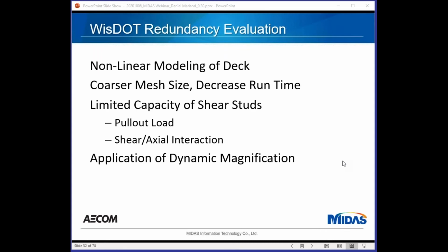So we had to make sure that those shear stud elements had not only pull-out capacity, but some sort of shear capacity. And then also we had to find out, when something breaks, we all know that there's a dynamic effect. So it's not only the load that is in the beam that gets transferred to the other part of the structure, but there's a dynamic effect too.